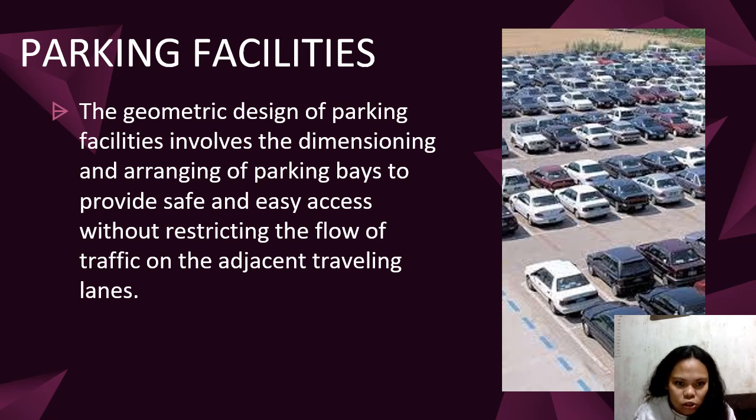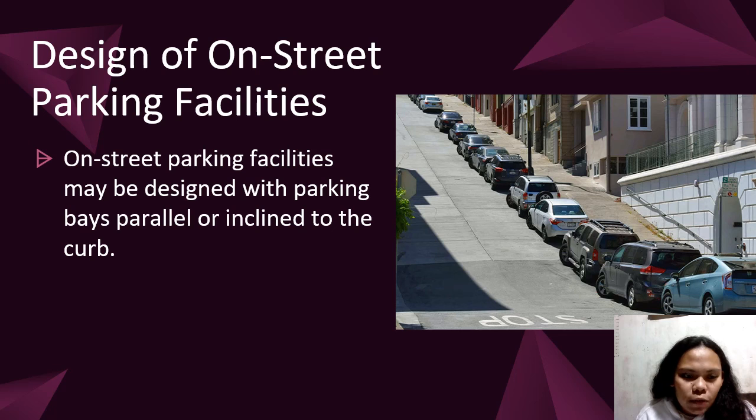So parking facilities. The geometric design of parking facilities involves the dimensioning and arranging of parking bays to provide safe and easy access without restricting the flow of traffic on the adjacent traveling lanes. So ang goal ng parking facilities is to provide safe and easy access without seriously restricting the flow of traffic on adjacent lanes. In design of on-street parking facilities, the parking bays may be designed parallel or inclined to the curb, as we see in the photo.